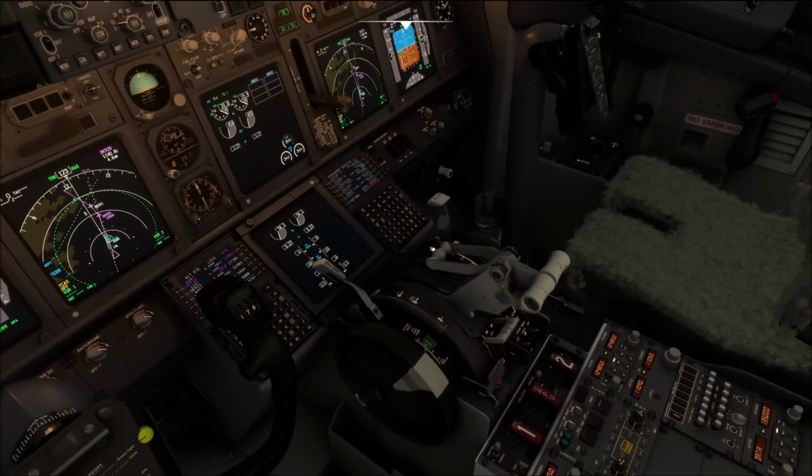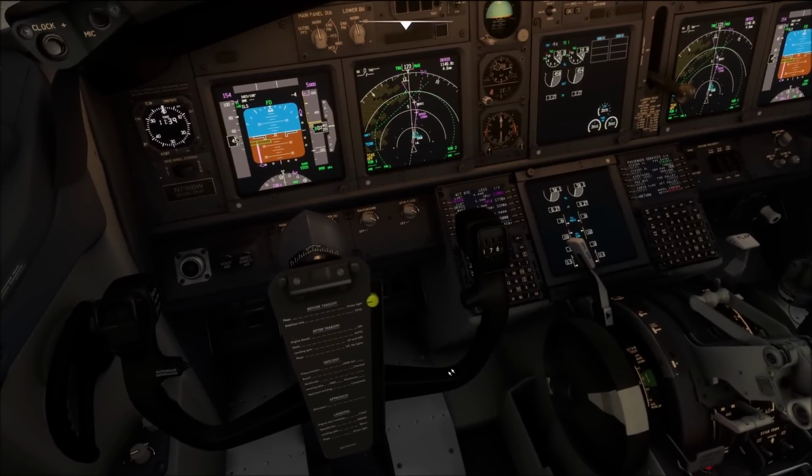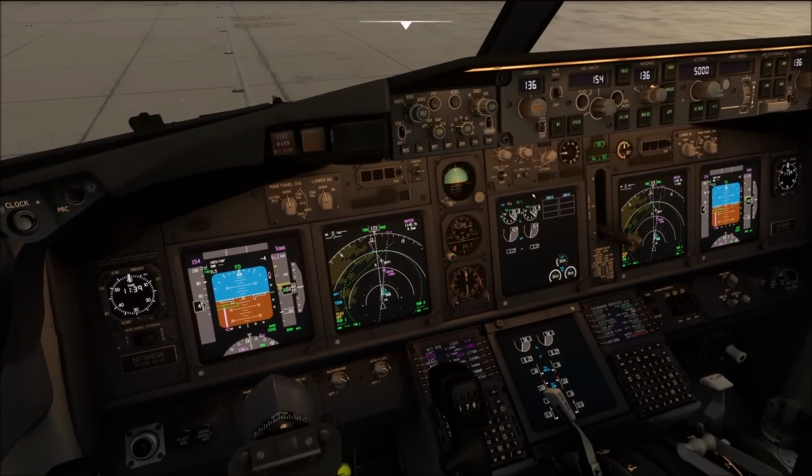So, for now the flaps are going to stay up. We will delay our flight control check and we carry out our recall, and then we run the before taxi checklist freezing conditions, which is going to take account of our airplane configuration not being in the same configuration where you would expect it normally to be. So let's talk about taxi procedures then.